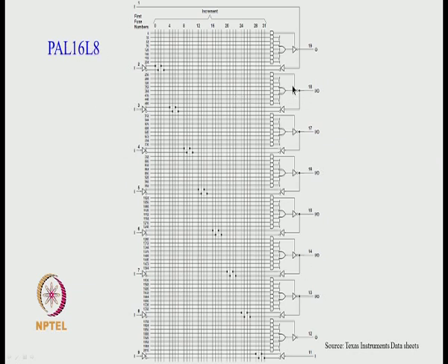L indicates an active low output. So it means that if you want to implement Y, then you have to implement Y bar as the AND OR part. That needs to be taken care of in the tool. You can see that, suppose you take this section, you have 7 AND gates, each has 32 inputs, but this is a wired AND gate. We will see that it's not a single AND gate with 32 inputs. You have a tri-state gate with enable, which an AND gate controls.